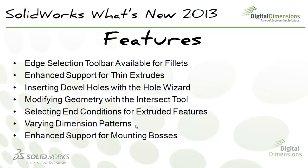So two more things to show you. The next thing is varying dimension patterns. So for circular and linear patterns, for features, you can vary the dimension, you can vary the spacing of your instances, you can vary the size, and you can even individually change some of these instances with the height, width, length of extrusions or cuts. And again, this works in circular and linear patterns. So I'll go back to SOLIDWORKS and show you that.